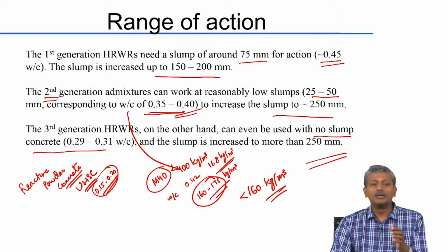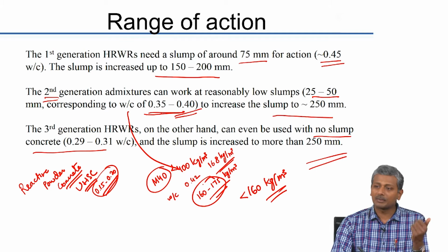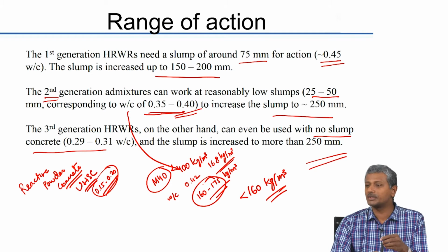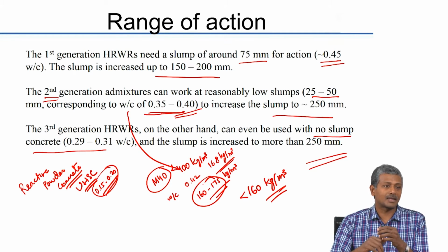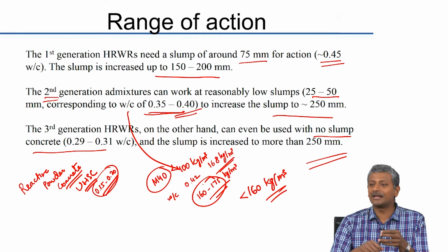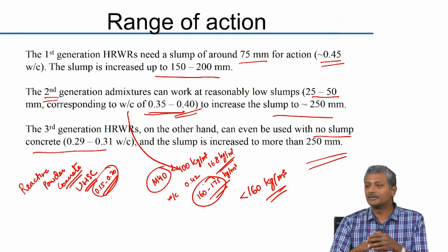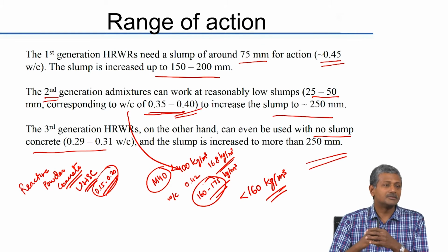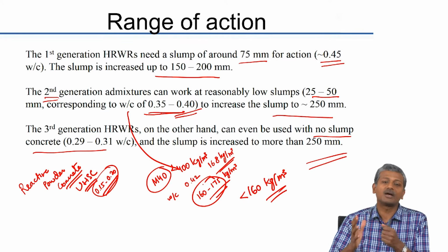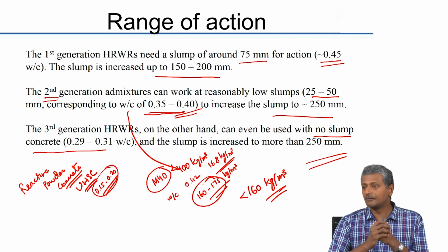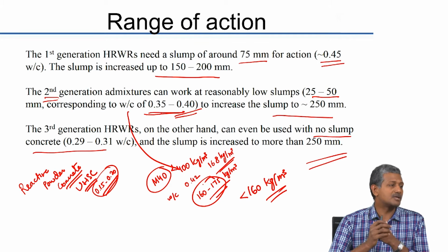Okay. So, when you do go to job sites, when you start practicing concrete technology, ensure that mixing time is enhanced when you are dealing with special mixes. Okay. Everybody will tell you that it's reducing their productivity, but I do not think that is true. Okay. So, if you operate the concrete mixer continuously, you need to ensure that each batch of concrete is at least getting mixed for at least 5 minutes. 5 minutes is a good time for most concretes to have a uniform consistency.